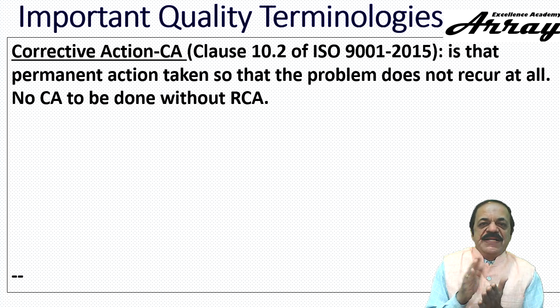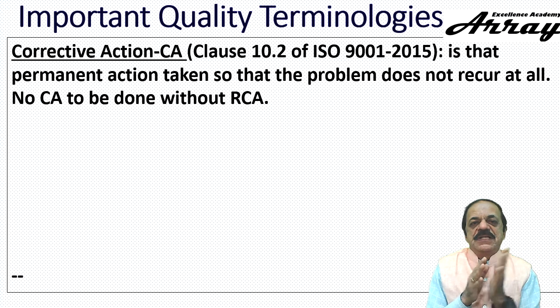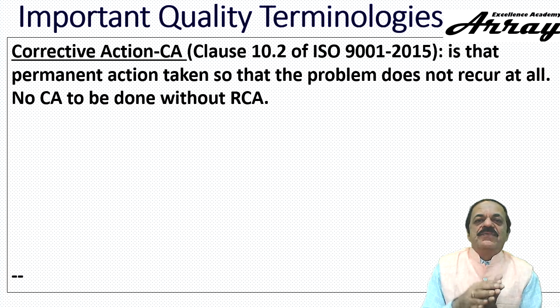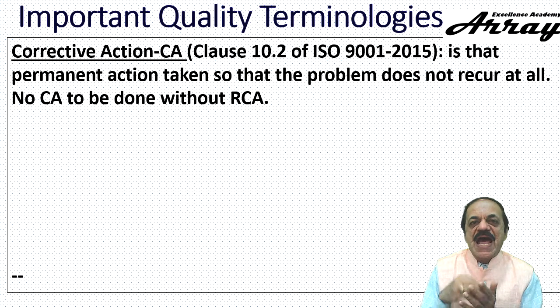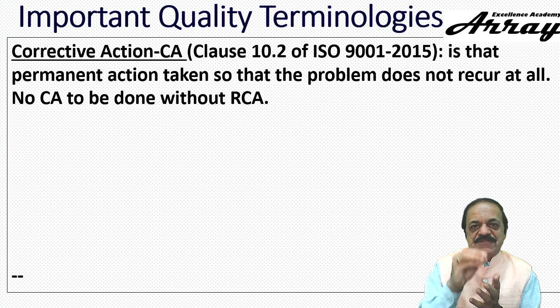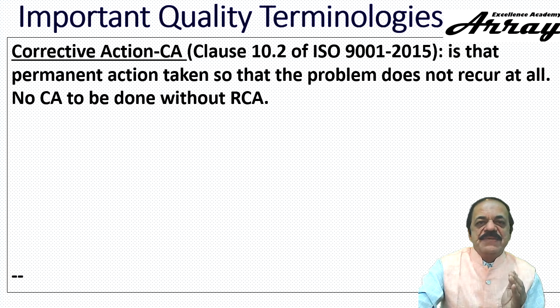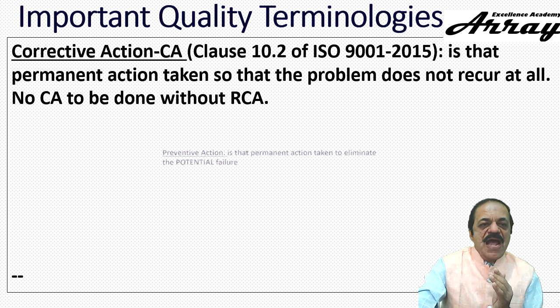Now, defect repair is a correction. Why did we understand this? Because though we ensure good items are going to the customer or into production, in the next lot, the manufacturing process produces the same defects. That's why it is temporary. Whereas corrective action, you do the root cause analysis, then you come out with corrective action, and then implement the improvement in the process, which is the cause for permanent improvement, and this is called as corrective action. Please be very clear what is containment, what is correction, what is corrective action.